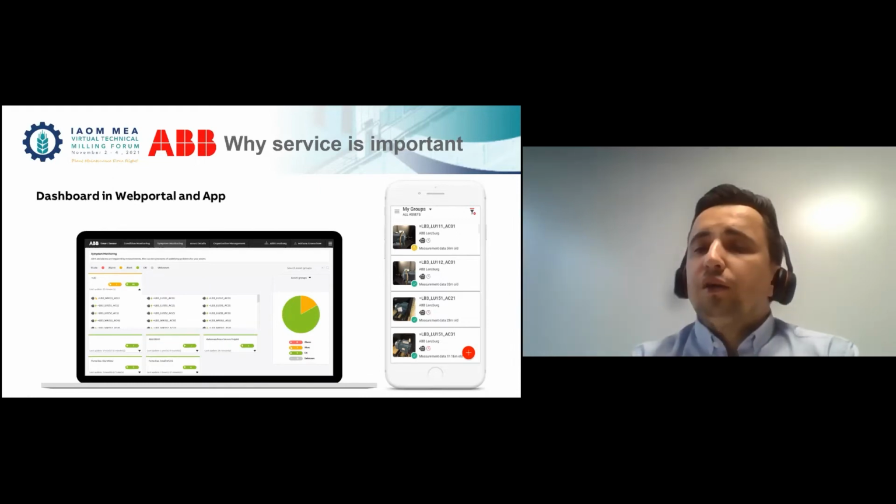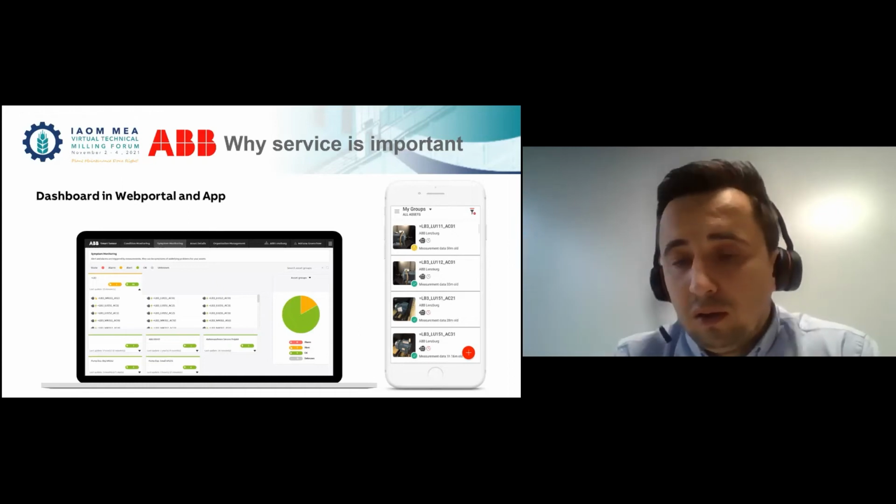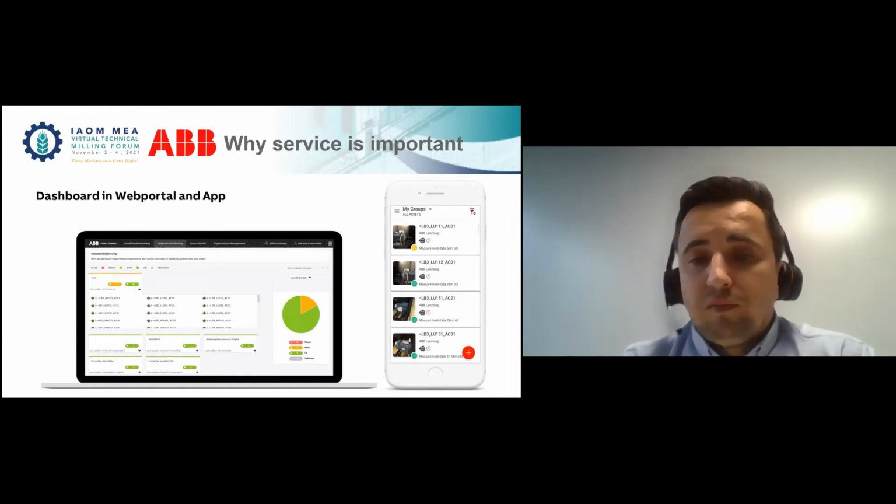Is the vibration too high? Is the temperature too high? And you can react in a very proactive way, avoiding a failure or a breakdown in advance. Once a year you can do an extensive measurement.